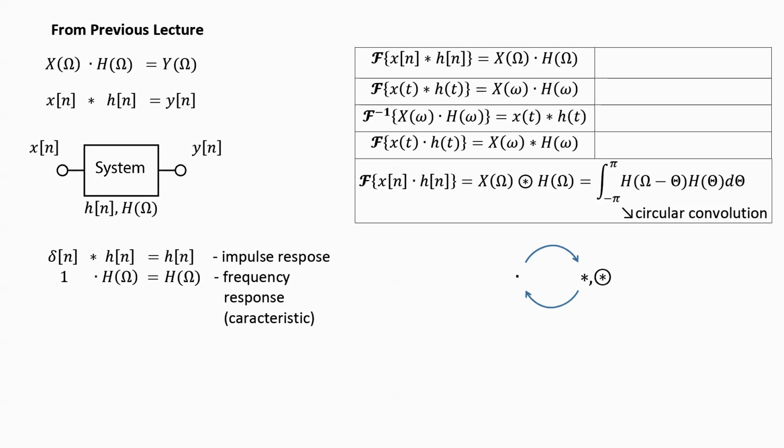On the previous lecture, I talked about filtering in the spectral domain. I told you that we can take the spectrum of our signal, multiply it with the frequency characteristic, and get the altered spectrum. And by doing this, we can, for example, suppress power noise interference or get bass and treble of our music adjusted. I also showed you that this is equivalent to computing the convolution in the time domain. I can take the input signal, compute the convolution with the impulse response, and get the filtered signal.